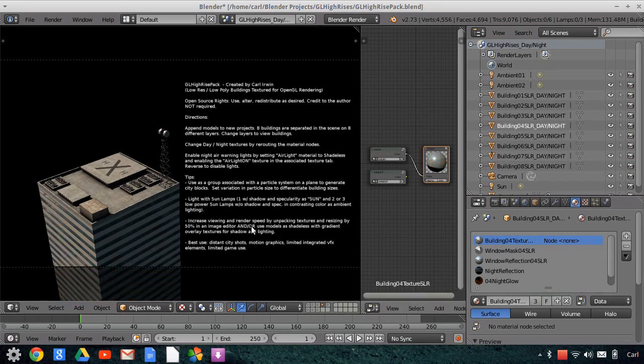And you can, of course, change the lighting in compositing. You could do a render pass where everything is darkened, no lights, no lighting in the scene, and just the lights turned on. And then you can change the color of that render pass and enable that in compositing as a different color, or change the color of the windows however you like. The illumination is kind of a yellowy kind of glow by default.